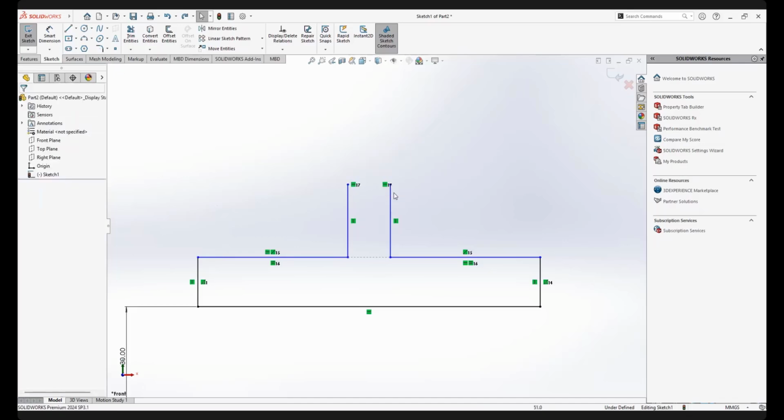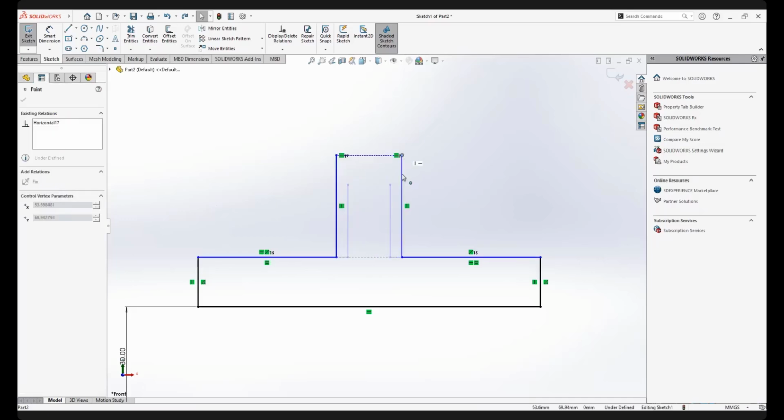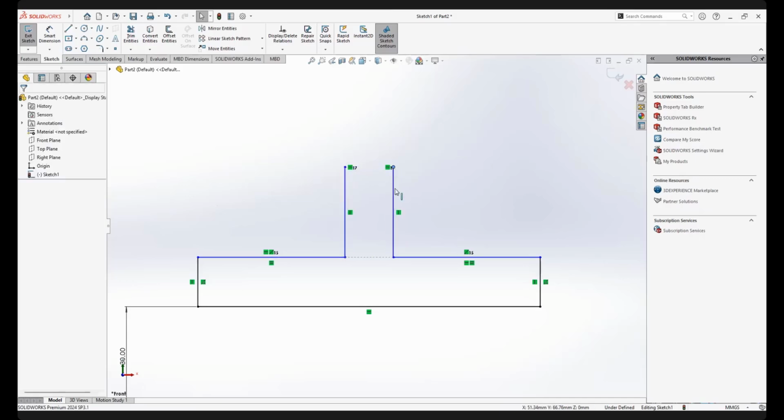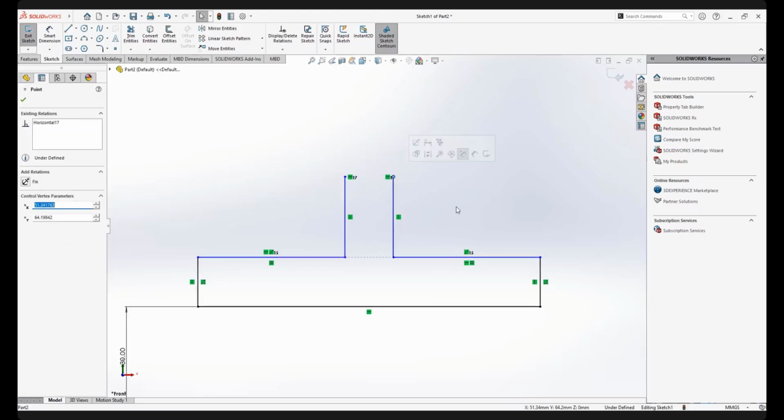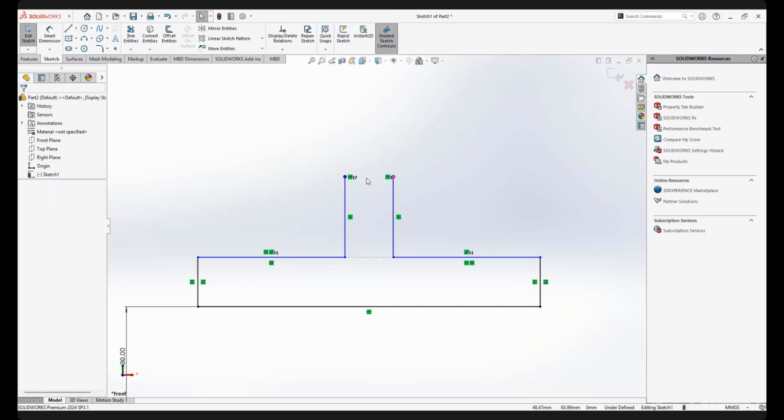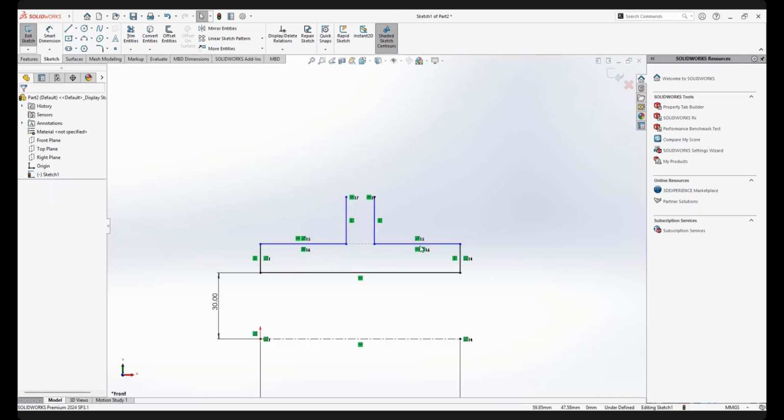Understand, class? You maintain horizontal. So do I need to set equal here? No need, because it will follow horizontal, right? Clear? I don't need to set equal. You would over-define the relation because it already follows. Automatically it becomes equal because I set this one and this one horizontal. Okay, I hope you understand that. So this is actually easy. You just play around with it, all right?